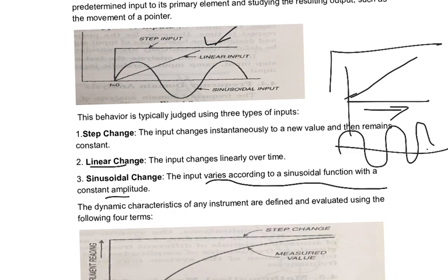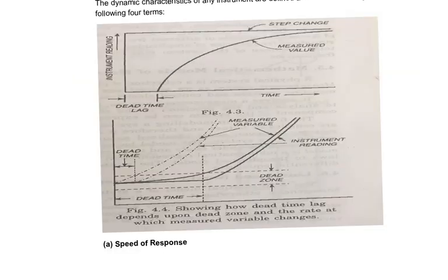So that is called as dynamic characteristics. Okay, let us look into it. Next, in the dynamic characteristics of an instrument, there are a few characteristics according to how the input has been varied. These are the speed response, lag, fidelity, and dynamic error. You have 4 dynamic characteristics of an instrument, in which, by giving a few inputs, the output will be evaluated.